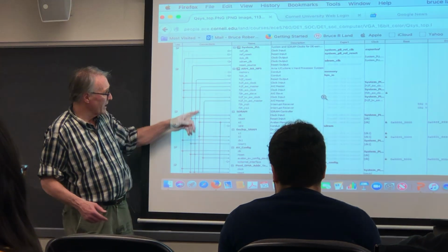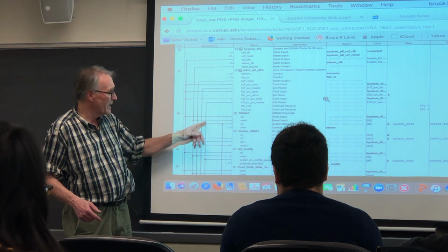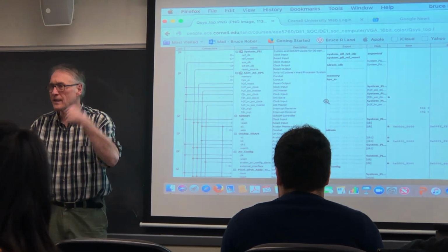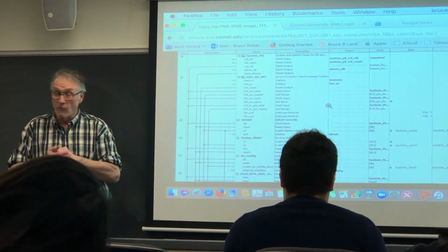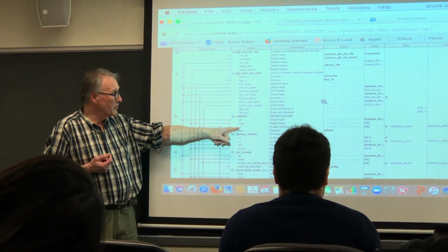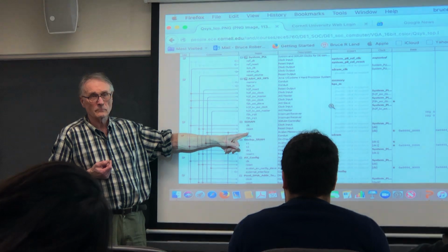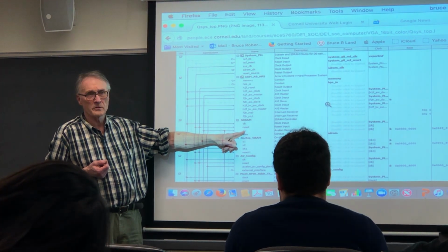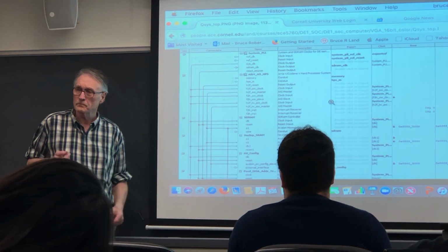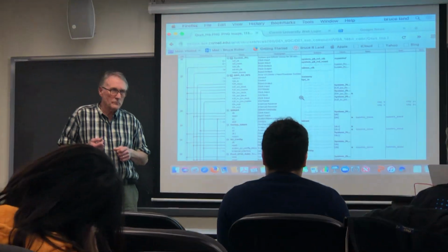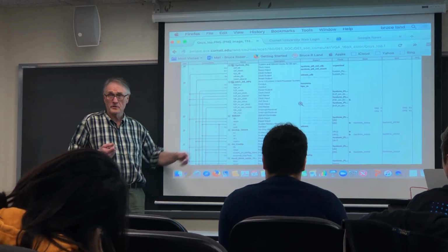Obviously, if you have two masters hooked to the same slave and you start pounding on this thing as hard as you can, you may overload. You may get to a rate at which this SDRAM can no longer read and write. It'll go at 100 megahertz, but you could saturate it. Particularly if one of these is a DMA burster.